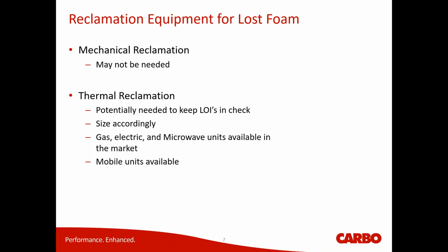Thermal reclamation, again, is not always needed, but is usually a good thing to think about with lost foam, and that's to keep your LOIs in check. Why is that? Most of the time, your casting process can burn up all of the carbon from the styrofoam. If it's not and your LOIs are creeping up, then you need a thermal unit to help burn that out and keep your LOIs in check.